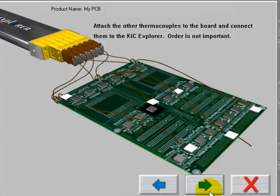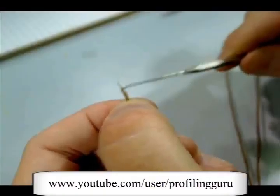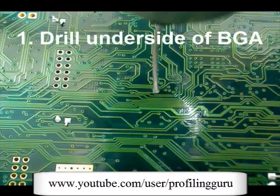Go ahead, mount the remainder of your TCs. For most PCBs, 3 to 5 is the average number required. There are units available on the market that allow for a much greater number of TCs. If you'd like to learn more about TC prep and attachment, you can find videos on this subject on YouTube at the following link,